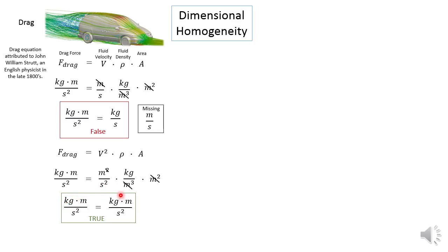And what's really interesting about this is the final drag equation that we use even today is so close to what he got. The only difference is that we have this CD here, which is a drag coefficient. It takes into account the shape factor and the different surface finishes of the vehicle that affect your drag, but it's a dimensionless coefficient, which is why it didn't come up in his dimensional analysis. But he was very, very close, and we still use this drag function today.